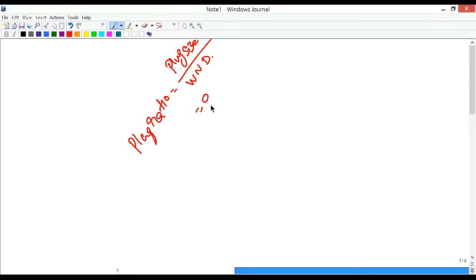Okay, so you don't melt the electrode, or oxidation of copper is also not going to happen because the electrode temperature seldom goes higher, because you also have water circulation inside the electrode. And diffusion of copper to steel, I put this deliberately, the copper diffusion into steel is extremely sluggish. Okay, it's never going to happen. So the answer for question 8 is the diffusion of zinc to the electrode surface.